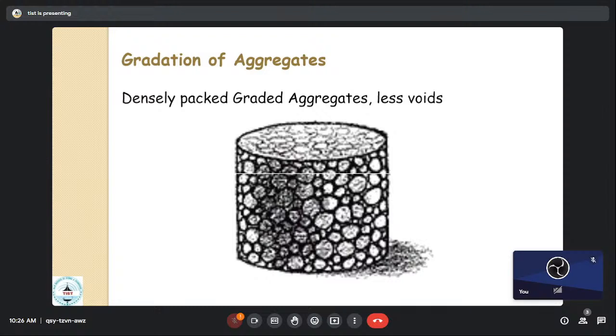For example, you can take a glass jar, fill it with equally same type of aggregates and observe it. You will find each and every pore in between, right? Yes or no? To fill those pores, you can have smaller size aggregates. And the pores still existing will be filled by fine aggregate, and in between that you will have your cement and water slurry.